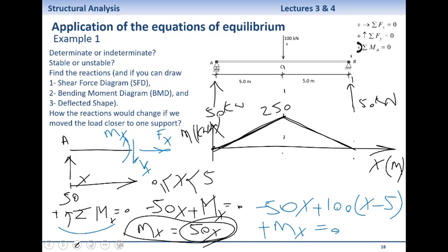So the beauty of this diagram is that with a glance, it tells you a lot about this beam. For each and every point in the beam, now you can look at this diagram and tell me how much bending moment you have and in what direction. It gives you the direction because we picked a sign convention, we are following that sign convention, and it gives us all the magnitudes that we need.